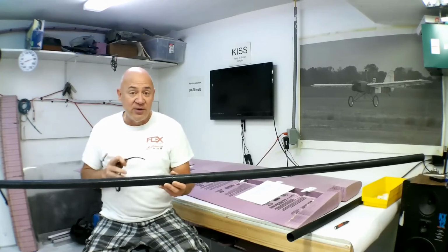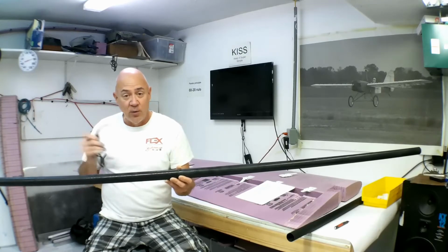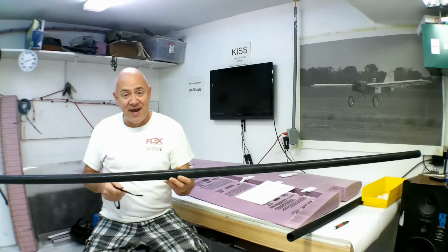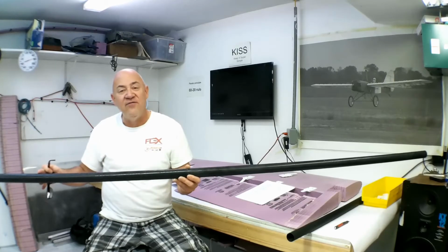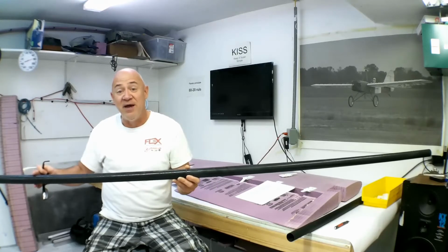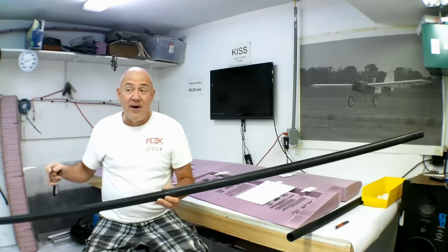So the way I do it, and this has worked pretty good, is if I want to test it for 10 Gs, I'll take the weight of the fuselage, divide it in half, and then put that weight on each wing. I think it's 55% of the way out of the span of the wing. And if the wing doesn't break, you're usually pretty good. Now, I don't know if I'm under or over much.